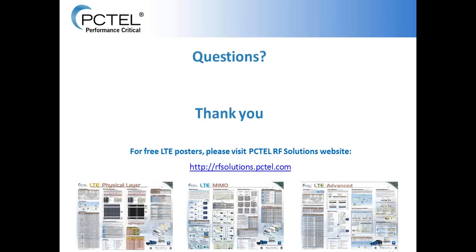So the first question that we have is, what frequency range can Seawave test? Jim, you want to take this? Sure. It's really dependent upon the scanner that you have. We've designed the log periodic antenna to go from 690 megahertz to 6 gigahertz. And you can use any Yagi also that you can find off the shelf. So it's dependent upon both the antenna, and then it's also dependent upon what your scanner has in it.